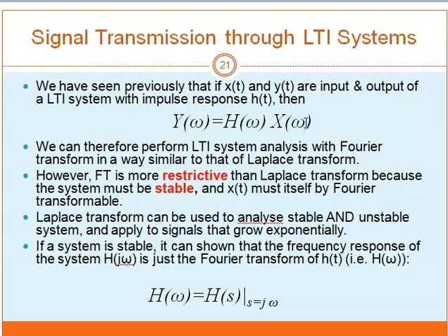that grow exponentially. If a system is stable, it can be shown that the frequency response of the system, H(jω), is just the Fourier transform of h(t), or H(ω). So H(ω) is equal to H(s). The Fourier transform is equal to the Laplace transform provided that s is equal to jω.